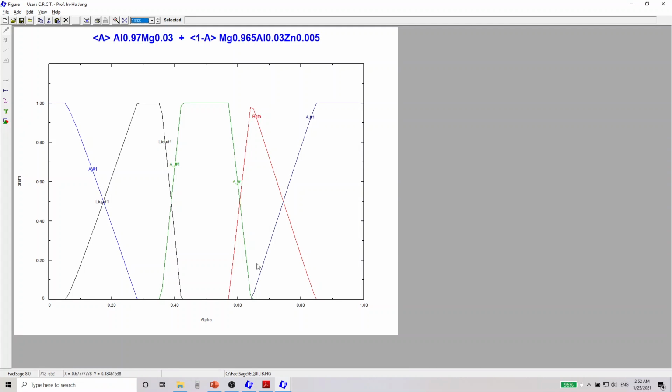Here in the plot, in the figure module, FactSage plotted all the data, as you can see, from pure AZ31 to pure aluminum magnesium alloy. In the interface region, what type of phases are formed at what composition is shown in this figure, and that is how we can calculate a simple interface calculation for a diffusion couple.